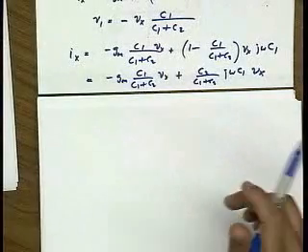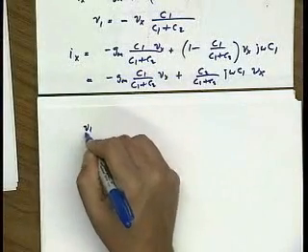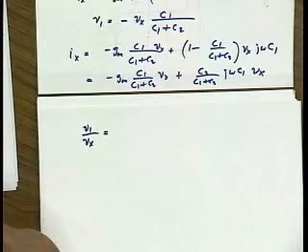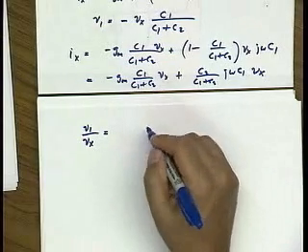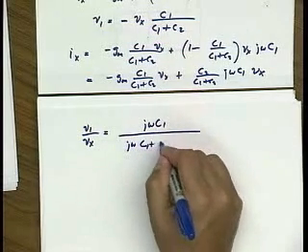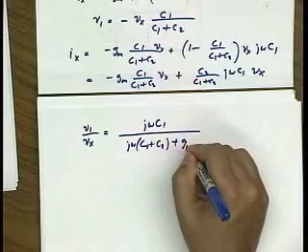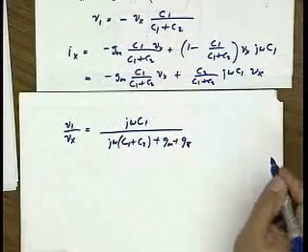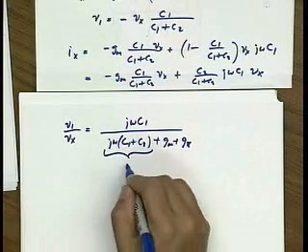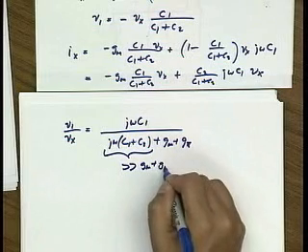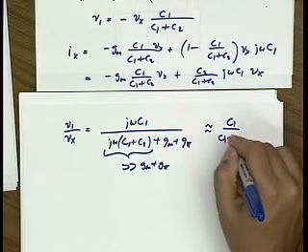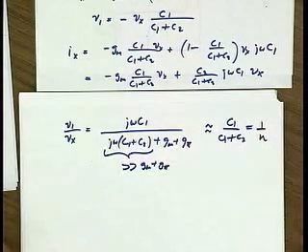Basically, let me just look at this assumption that I make. I'm assuming that the transfer function from V1 to Vx, I can actually analyze this exactly. The transfer function exactly is j omega c1 divided by j omega c1 plus c2 plus gm plus g pi. Okay? And so you can see now the assumption is that this term is much greater than gm plus g pi, right? And that's when we get this approximation. In other words, 1 over n.